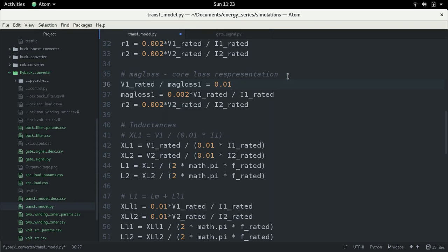That is, if rated voltage is applied across the winding, a 1% loss current will flow across this loss winding, right? Maybe that is a little high. Let me change this to 0.5%, right? So this has to be 0.5 times the rated current.